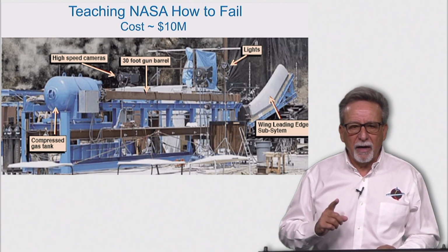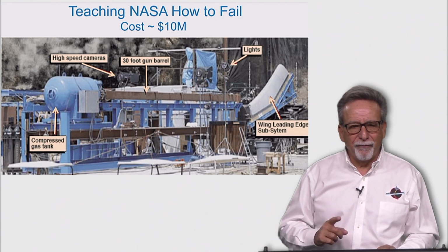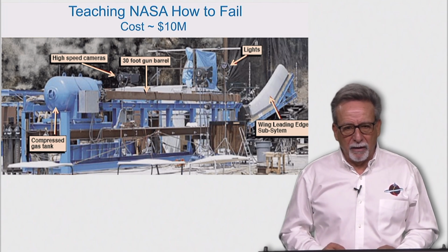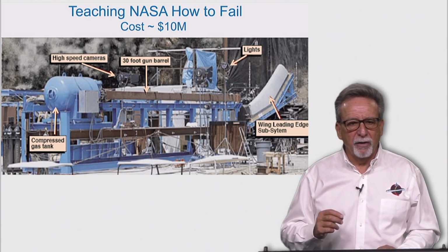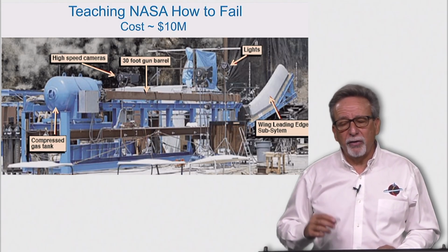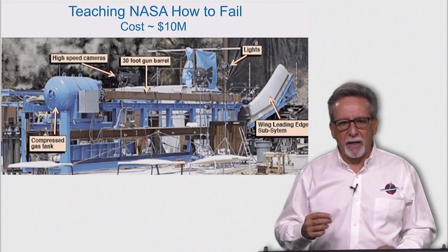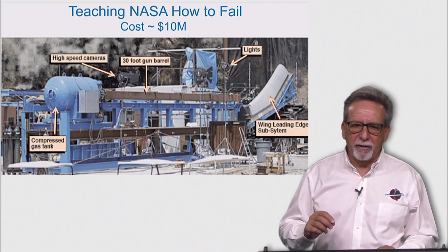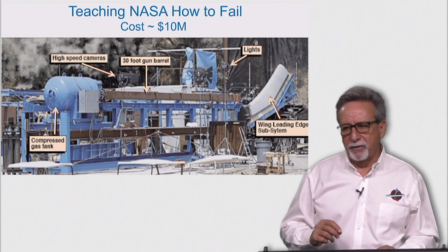a binary answer. If that one test with a 1.67 pound piece of foam traveling at 545 miles an hour could cause critical damage, we would not have been able to validate our modeling and simulation methods, and hence if we wanted to vary any one of those parameters, for example, the size, shape, velocity, angle of impact, we would have had to run another very expensive test. This is not the way to collect data and to construct knowledge. Also, because it took so long to create the experiments, it would have taken months before we were able to learn anything which could help us understand the problem.